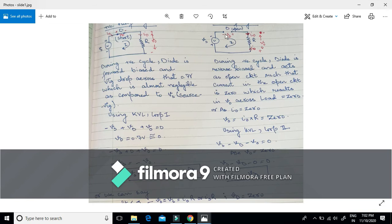Since no current flows in the circuit, the voltage drop across the load, that is I naught into R, is equal to 0, since I naught is 0. That means V naught is equal to 0. Across this open path, the voltage across the diode will be equal to the source voltage. During this negative cycle, the voltage across the diode equals the voltage across the source, and V naught is equal to 0.